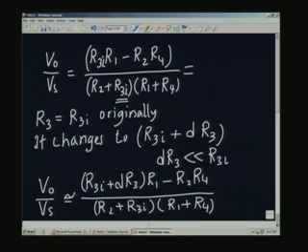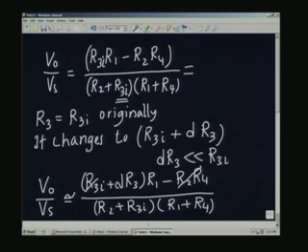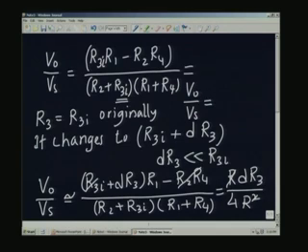Actually, we had done this exercise earlier, I am just recapitulating, and you remember that R3I times R1 minus R2 R4 must be cancelling each other, because that is the condition for balance when there is no strain in the strain gauge element. Therefore, this portion is going to cancel off with this. So, you have R1 dR3, and now I will assume that all these R's are the same, because R1 is equal to R2 equal to R3I equal to R4. So, let us assume that they are all equal to some value R. So, I will say this is R into dR3 divided by R plus R, 2R, this will be another 2R, this becomes 4R squared, and one R will cancel off with this. So, you see that the ratio V0 by Vs will become dR3 by 4R.